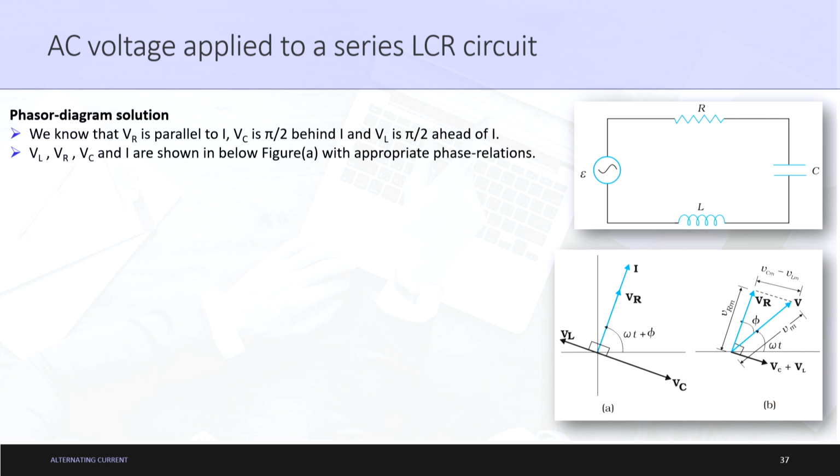Till now what we know is that we are trying to solve this equation using the phasor diagram solution. The main requirement here is that we should know the value of Im and the value of φ. The basic given assumptions were that the voltage across a resistor is VR, across a capacitor is VC, and across an inductor is VL. So, now let us start the solution here.